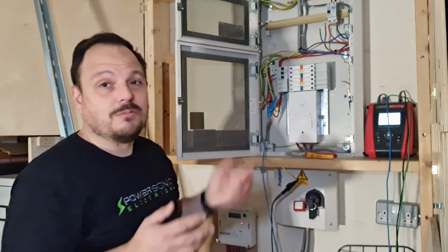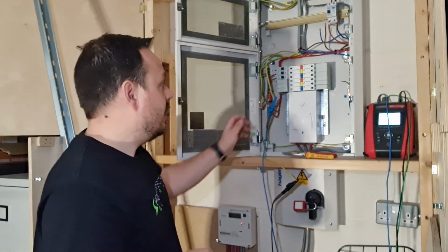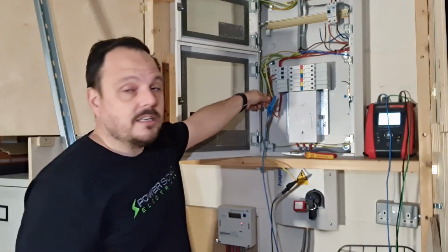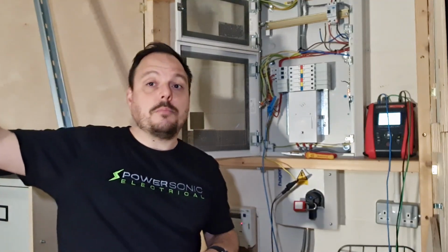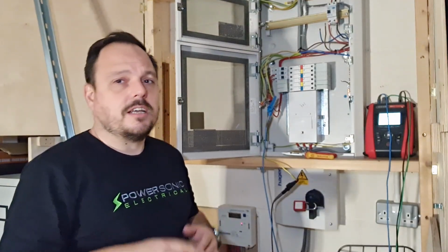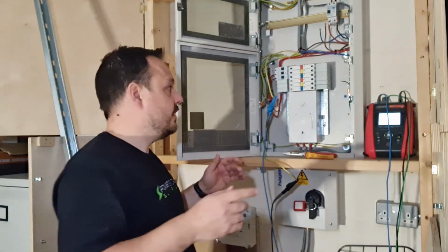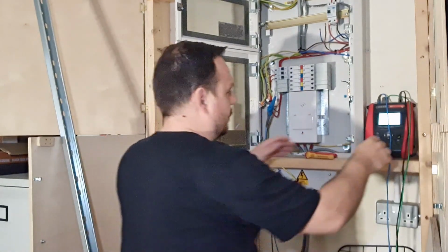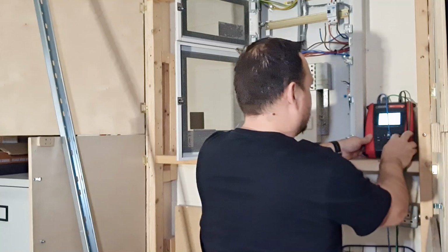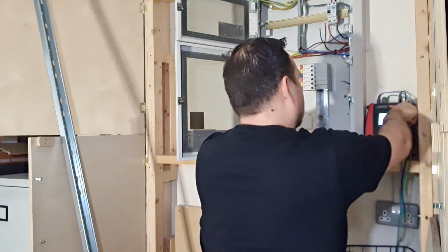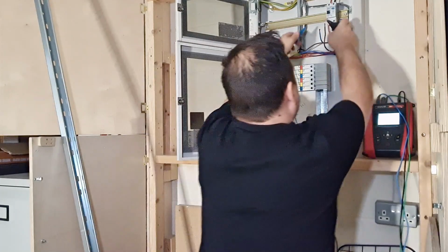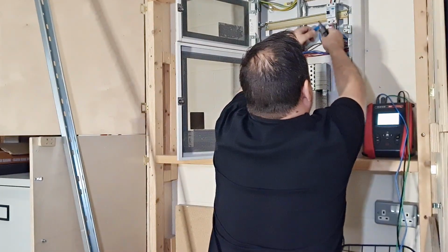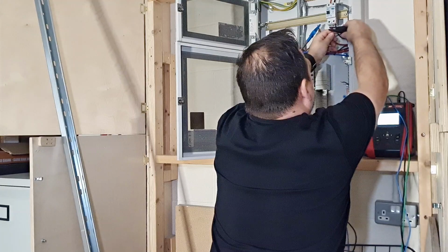But before we do that, we'll just quickly gather the end-to-end data. I have also already linked out the line and CPC on the lighting circuit, so that's ready to go and take a measurement over at the end point of this lighting circuit, and we'll show you that in a second. But I'll just run through the end-to-ends. I've already clipped onto the CPC, so we'll do that one first. It's 0.34 on CPC. We would expect the lines and neutrals to be lower because they're larger conductors.